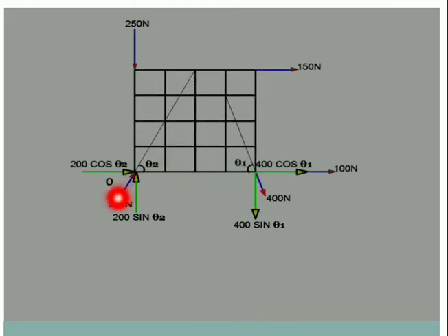For this force which is coming inward, the components are coming inwards. For this force which is going outwards, the components are going outwards. And here there are two forces now, because the 100 Newton force was already existing at this point. Further, the resolved component has also come on it. So there will be two horizontal forces at this point. Okay, so be careful.